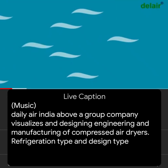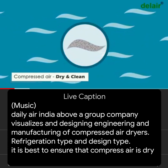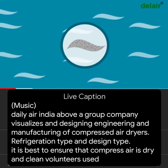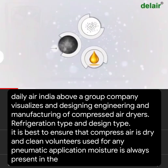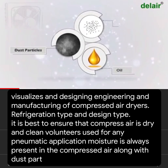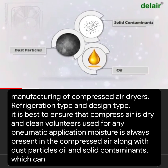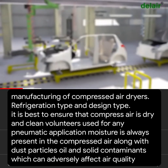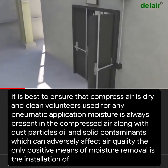It is best to ensure that compressed air is dry and clean before it is used for any pneumatic application. Moisture is always present in the compressed air along with dust particles, oil and solid contaminants, which can adversely affect air quality. The only positive means of moisture removal is the installation of a compressed air dryer.